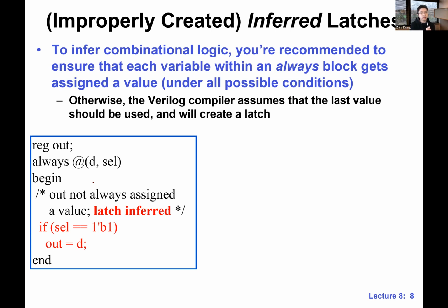you actually want to create a mux. You have an input D, and then you have a select signal. But if you write an incomplete if-then-else statement like this, the tool is going to infer a latch. Why is that? Anyone know? What's the intuition here? We already saw a latch example on EDA Playground. So why is this one a latch?